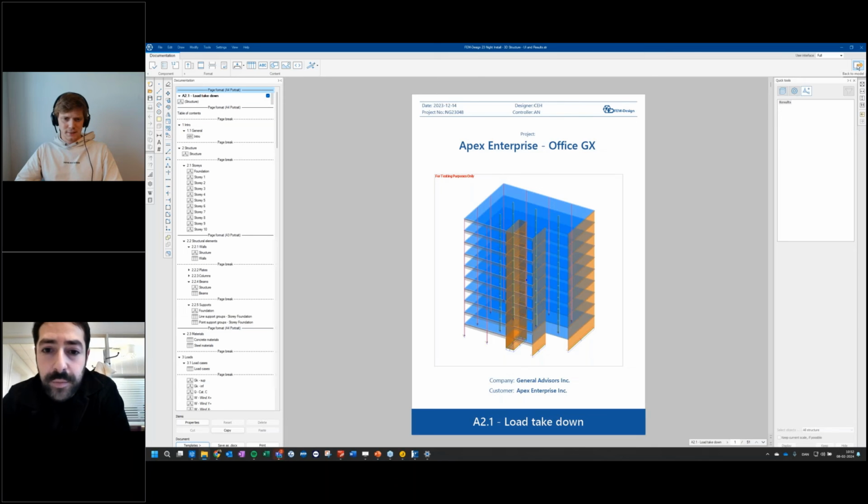Perfect. And then we got a question about the use of stirrups along the edge of the wall when you were showing the plastic analysis of the wall. As far as I'm concerned, we only add longitudinal reinforcement. But if you add the reinforcement and it touches the edge, it will be fully anchored. So exactly. If you add it on both sides and they are fully anchored, then it is acting as if it was a U-bar or a U-stirrup.